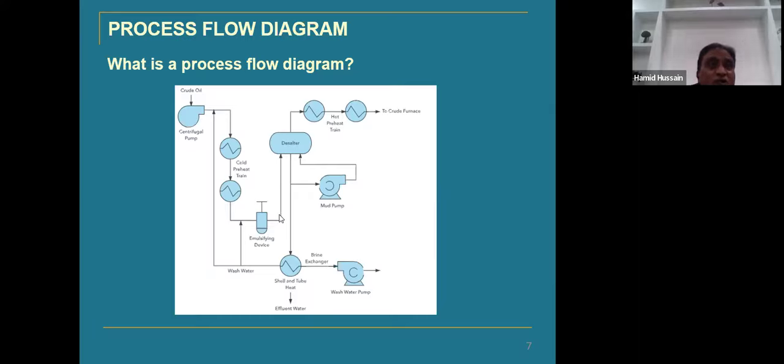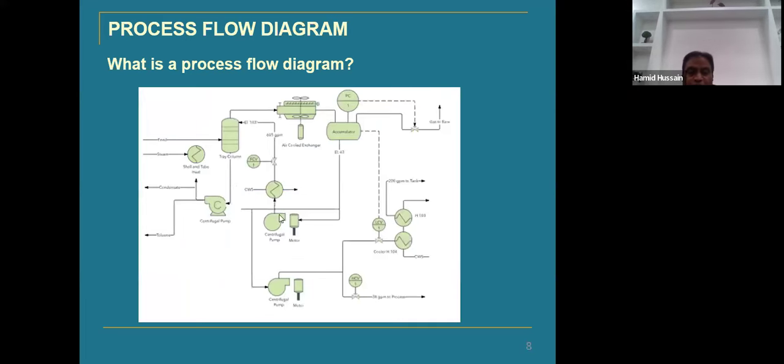Based on that, they can design their pipeline and decide what sort of flanges are to be used so that they can withstand that pressure and temperature. So we can say class 150 pound rating or class 300 pound rating. If you join our courses, then definitely you will know what those terms are. I'm just going through quickly.